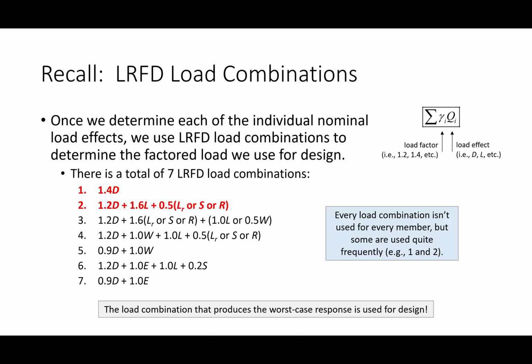We have our load combinations, and I think it's fair to say that for the vast majority of problems that we do in this class, 1.2 dead plus 1.6 live is going to be the situation that matters.